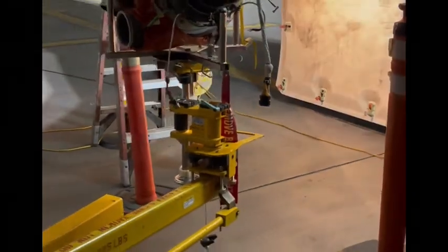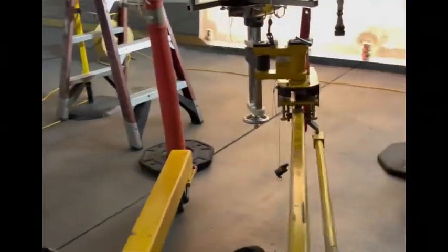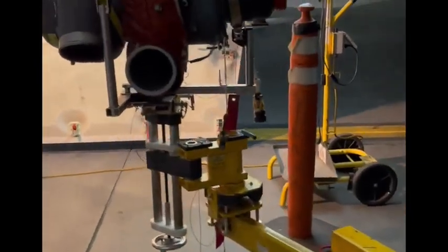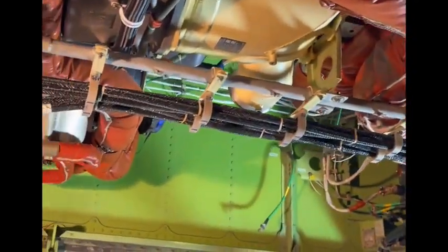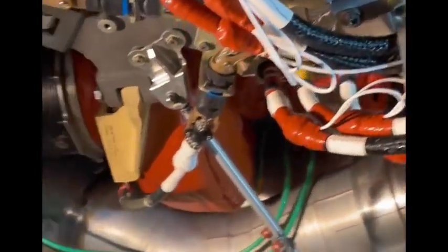If you have managed to stick around this long, you're going to see a pattern within the switches, because everything is set to auto or on. That's how the 787 functions. It is a very automated aircraft. Pack left, pack right, automatic. Trim air valves, automatic or on. Forward cooling equipment, recirculating fans, all in automatic.